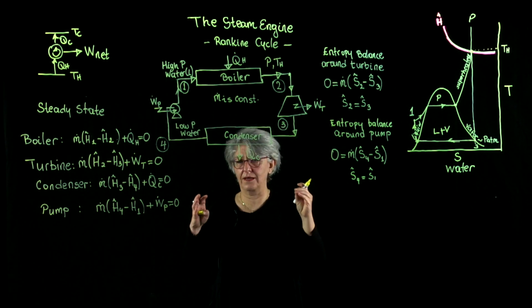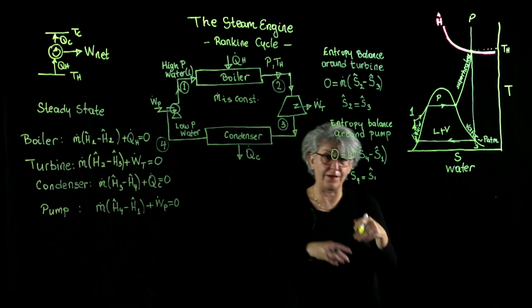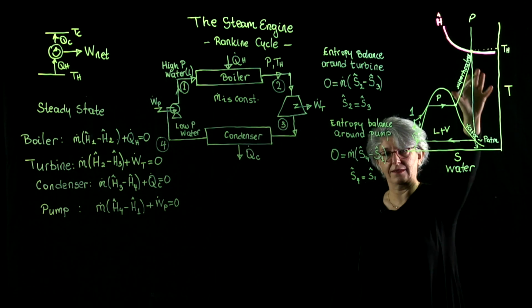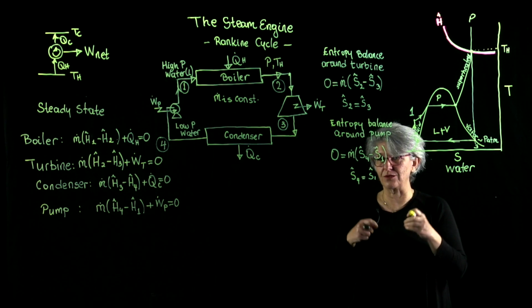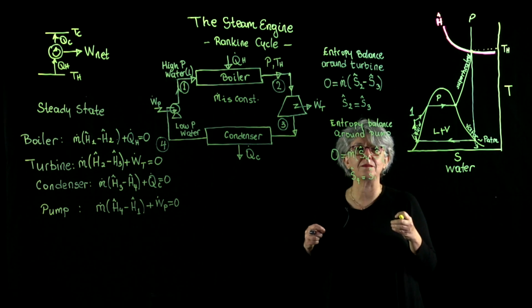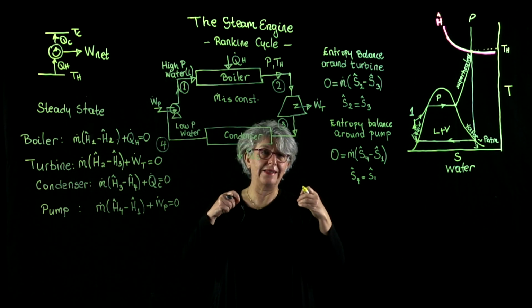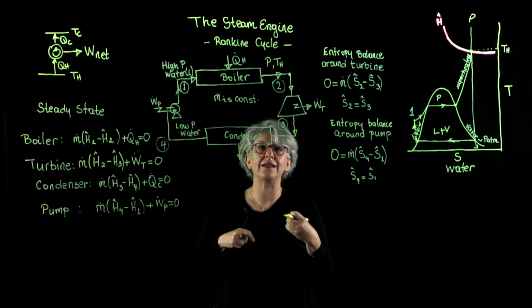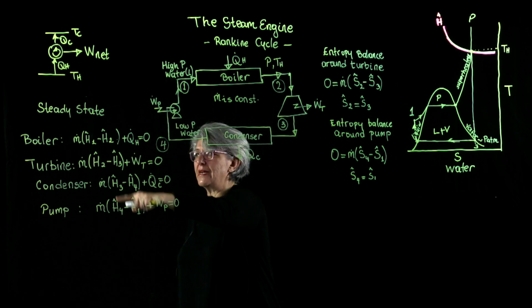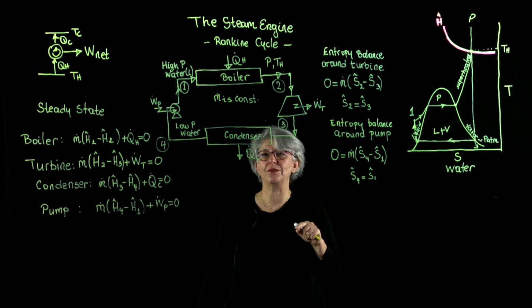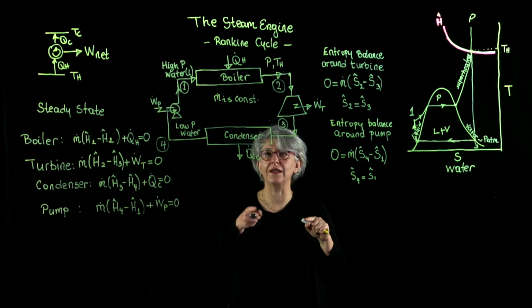I know my state variables. I have my energy balance equation. Right now I don't have my steam table or the TS diagram to number these processes, but I strongly recommend using the TS diagram of water, of steam, to design yourself Rankine cycles, choose your temperatures, choose your pressures, and evaluate the energy balance for each process unit until when? Until we calculate the efficiency of this cycle.